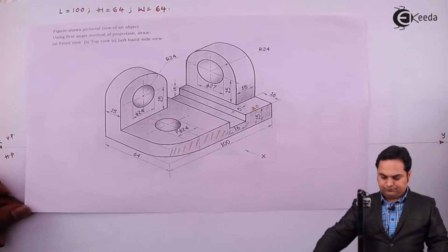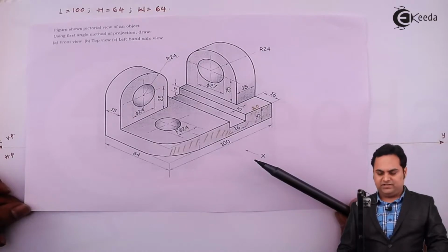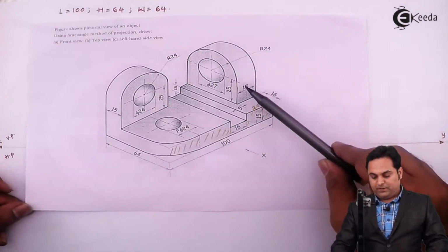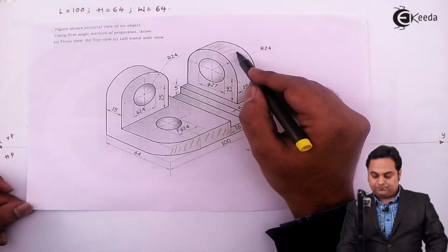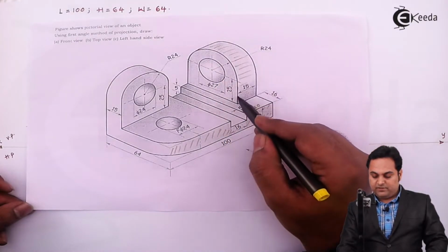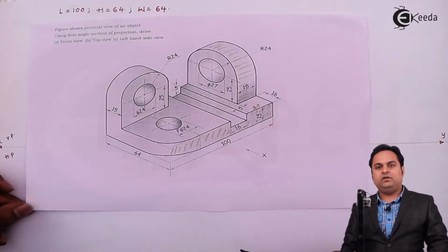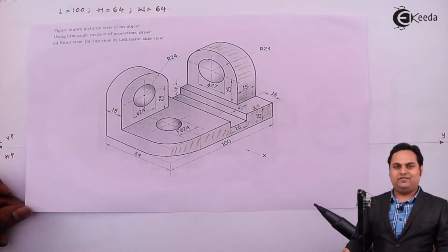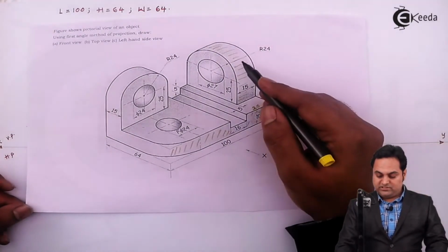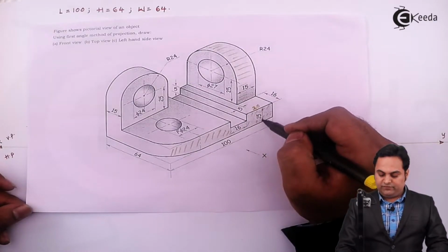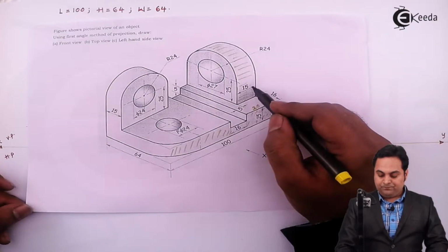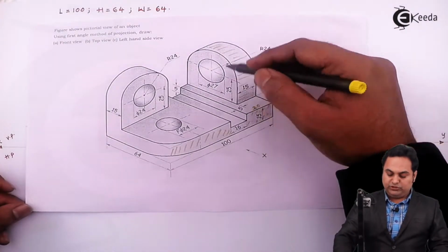After this, when we are looking along the x direction, this part, which is again the thickness of the semicircle, will be visible and it will be seen as a rectangle from the x direction, or we can say from the front view. Now this rectangle has a length of 15 and it is also starting after the 15 mm height block, length 15, and it will be up to the total height.